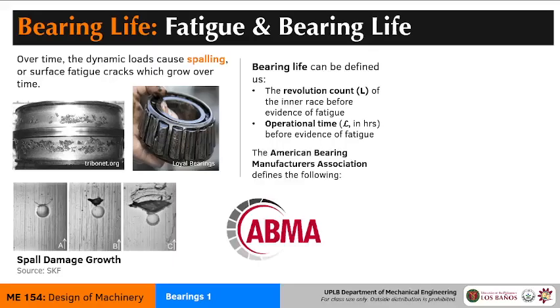So, okay, what do we do next? This concept of how long the bearing will last has been codified by the American Bearing Manufacturers Association, or ABMA. According to ABMA, they want bearings to be rated to a particular number of cycles. This number of cycles is known as the rated life, or curvy L sub 10. What is the definition of rated life?